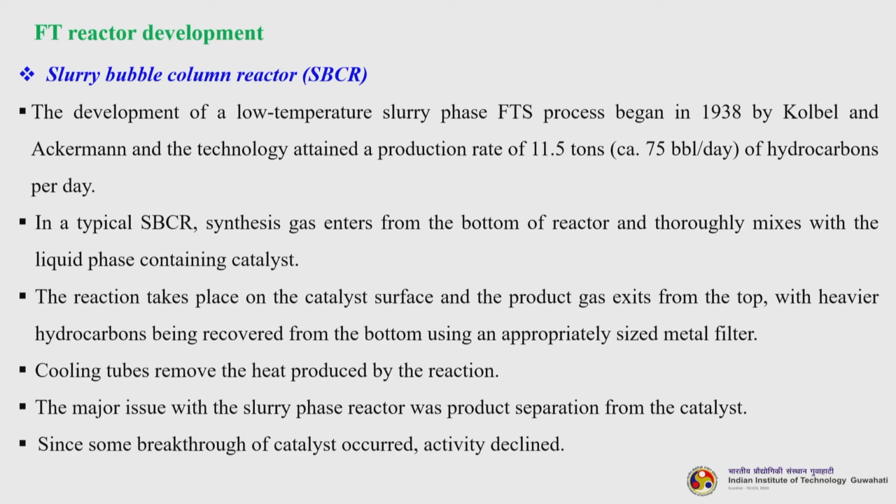the FT synthesis reaction. So, the slurry bubble column reactor, the SBCRs. The development of a low temperature slurry phase FTS process began in 1938 by Kolbel and Ackerman, and the technology attained a production rate of 11.5 tons of hydrocarbons per day. In a typical slurry bubble column reactor, synthesis gas enters from the bottom of the reactor and thoroughly mixes with the liquid phase containing the catalyst.